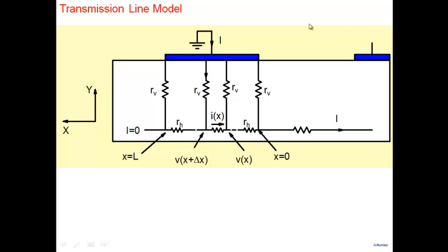How would you define it? The current is I. So what is the overall resistance? How would you define that? Can I say the voltage at this point, V at x equal to 0, divided by I will give you the resistance? Agreed? Because the voltage here is 0, and whatever is the voltage drop, the difference between the voltage here and the voltage here, which is V0, divided by the current flowing, will give me the overall resistance of this particular contact. Okay, so that's how we will calculate.